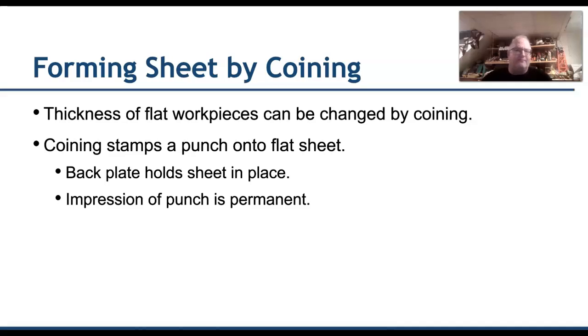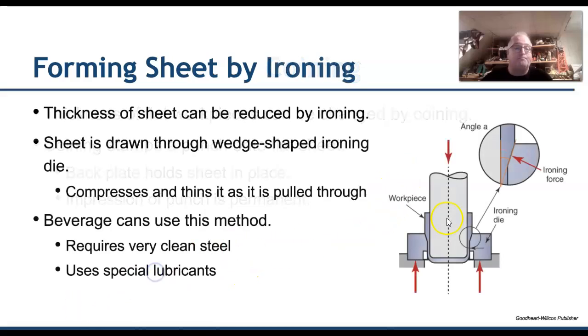For those of you who are welders, if you think in terms of the iron workers in the welding shop, that would give you a good idea. Sometimes we can use the punch there in the iron worker, and it's a great way to punch and get these coin shaped holes out of it. We're still left with the coin left over, but it also supports the material on all sides so we don't deflect or deform the sheet as well.